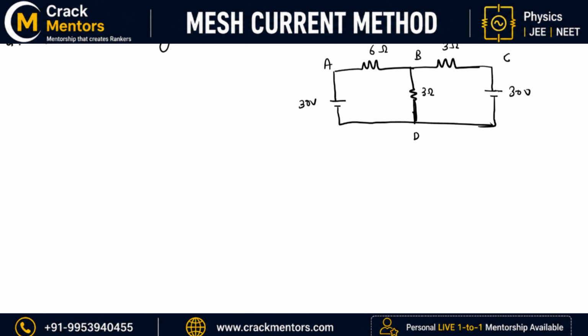Basically, if you want, you can do this question by 2 other methods as well. I will be telling you all 3 methods to solve this question. First, let us do it with the help of Kirchhoff voltage law. So let's begin with this. First I have to draw the direction of the current.